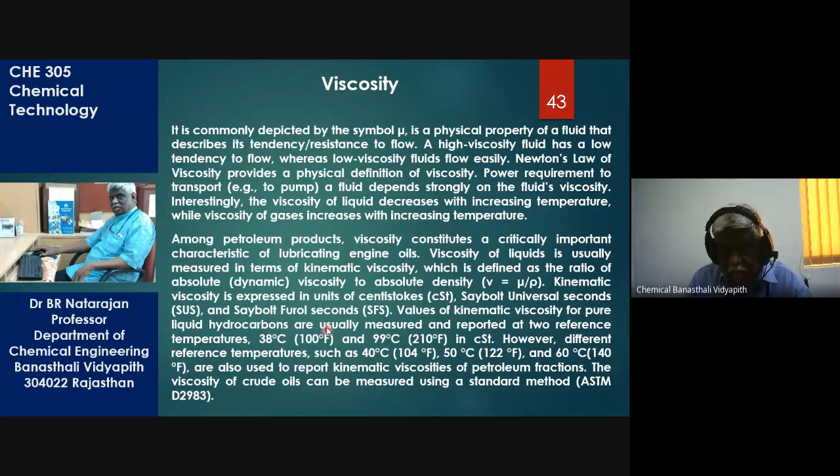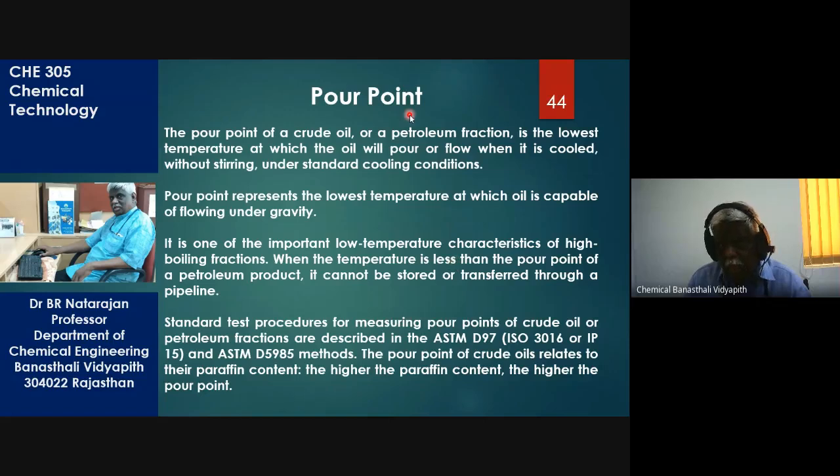So viscosity has got standard tests, right, which are prescribed by the ASTM standard, and the viscosity value is a laboratory experiment to calculate the viscosity, right? And pour point is the lowest temperature at which the oil will pour or flow when it is cooled without stirring under standing cooling condition. See, when I pour something, will it pour or not, flow or not? Suppose it is just sticking to the vessel and not flowing, highly viscous.